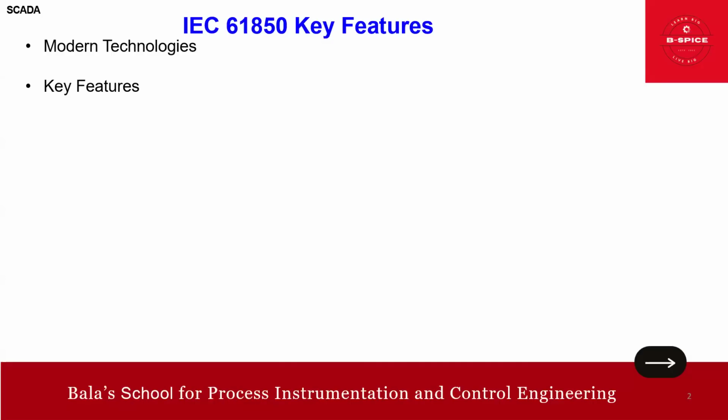It actually has many key features. For example, the use of VLAN, virtual LAN, and priority flag for GOOSE and SMV enable much more intelligent use of Ethernet switches. You may have a question here: what is GOOSE? GOOSE is nothing but the Generic Object-Oriented Substation Event.